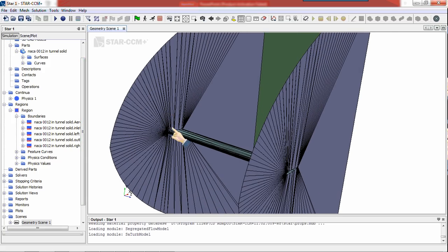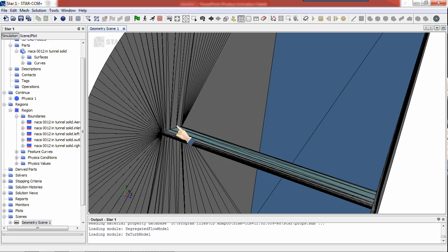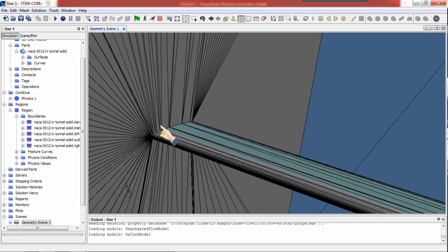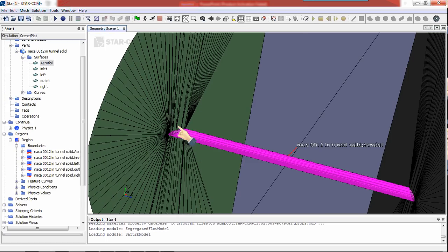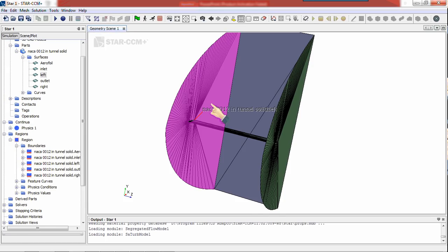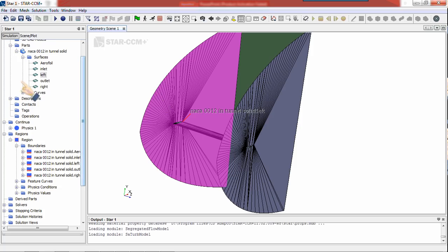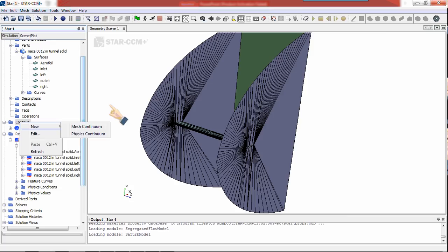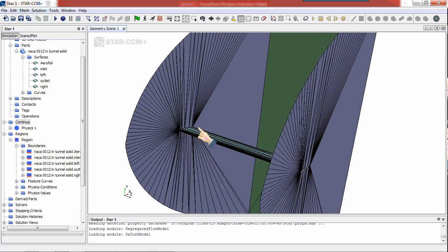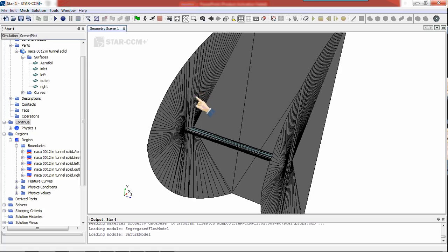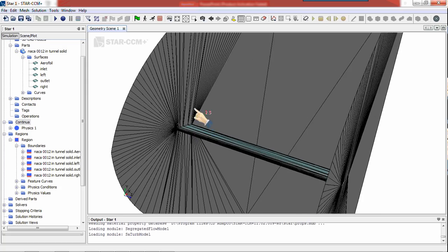If I choose a mesh modeler, many mesh modelers will do a fine mesh near the walls. So as of now we have every surface as a wall. If I mesh using the Star-CCM+ mesh modelers in the mesh continuum mode, then it will give a finer mesh wherever it is unnecessary.